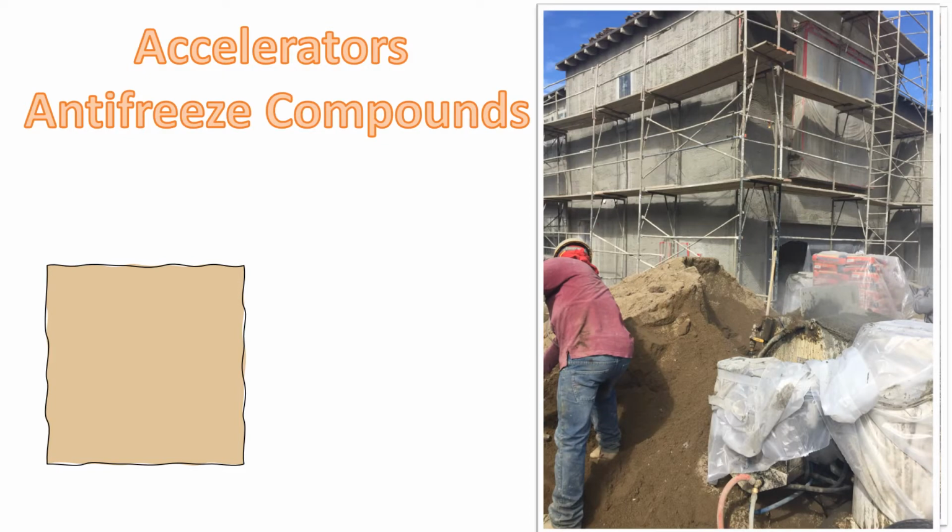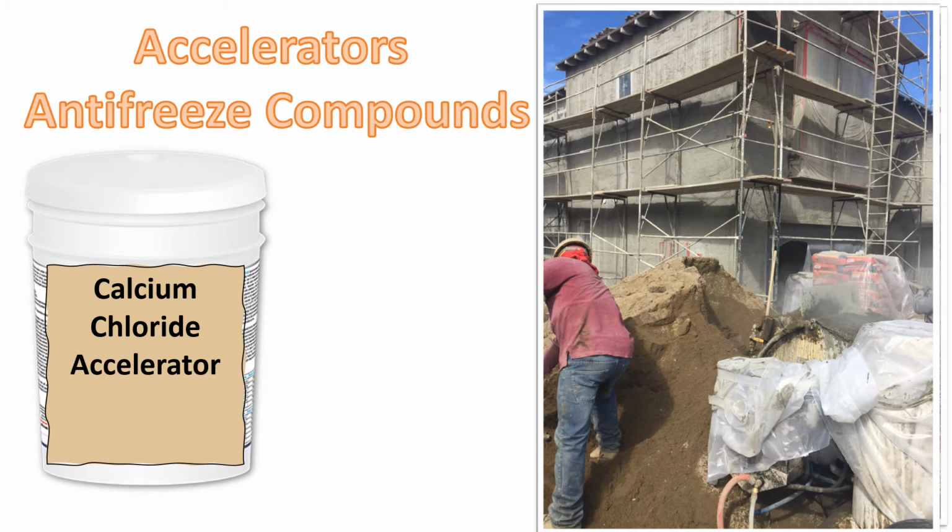Another additive is the accelerators or antifreeze products. They will typically accelerate the cure of the cement plaster. Some of these products are made from calcium chloride. This is a chemical known to rust metals. While fine for roads, block walls, or concrete with no metal, they can impact lath and metal trims. Thus, they are not recommended for the use of stucco on lath.